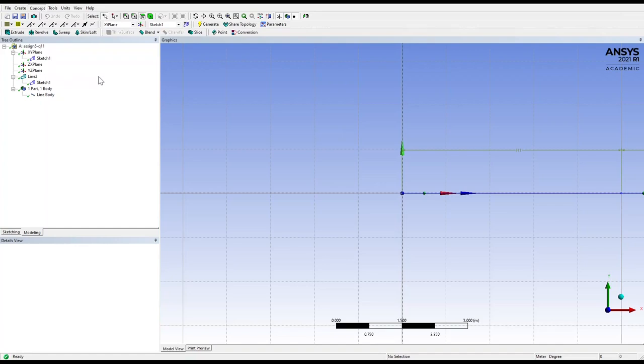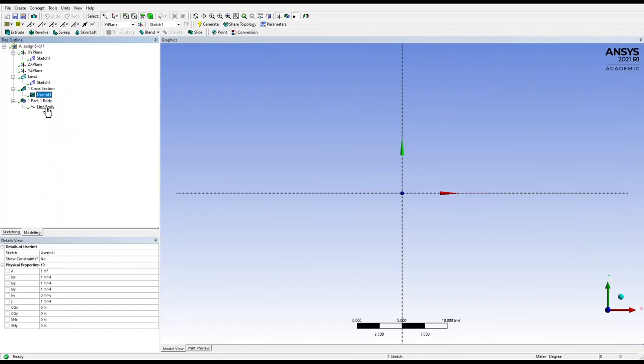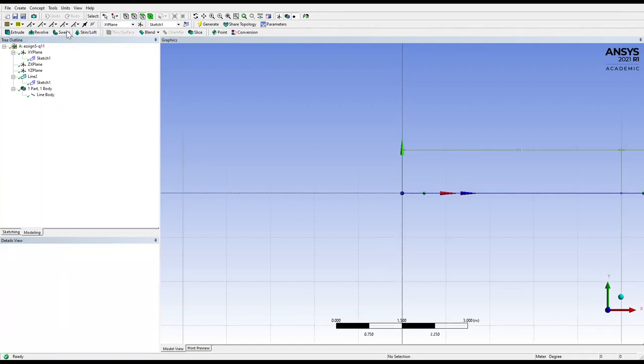The easiest one is rectangle. I use rectangular, or you can also use user integrated, where you need to fill in all these values, or at least some of them. So you need to know what IXX is. In this case, we know our IXX and our IYY, but we do not know our J here. So I'll do some trick here. Let me delete this one and define our cross section as a rectangular.